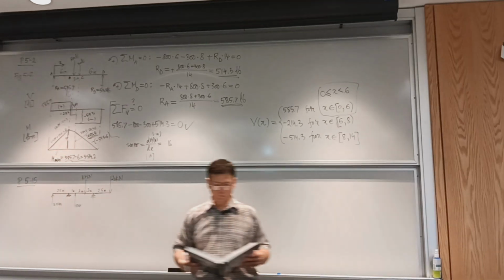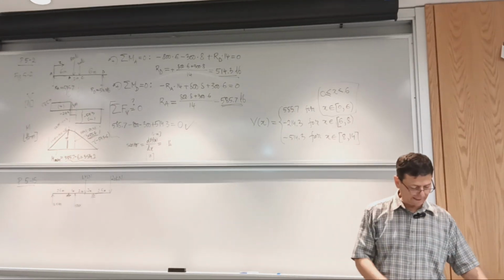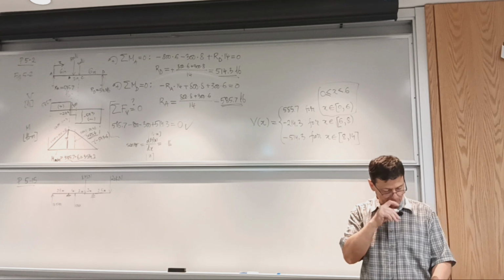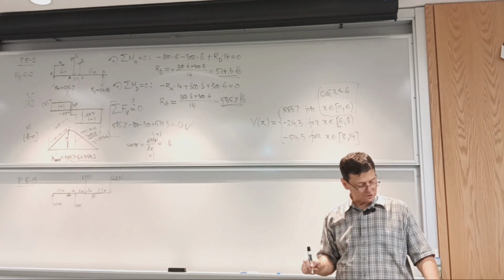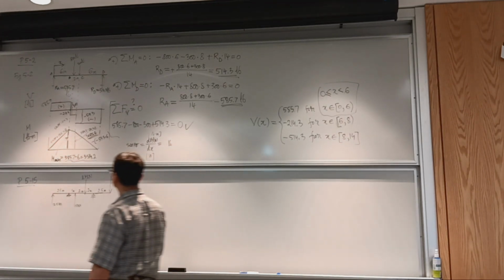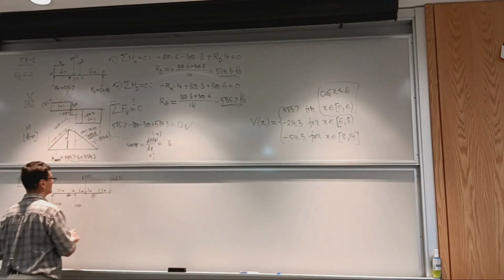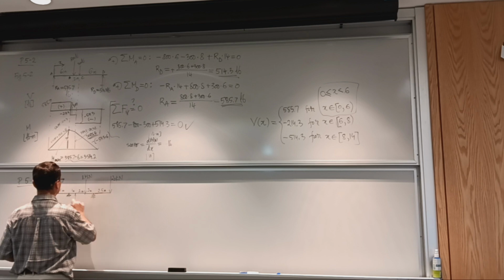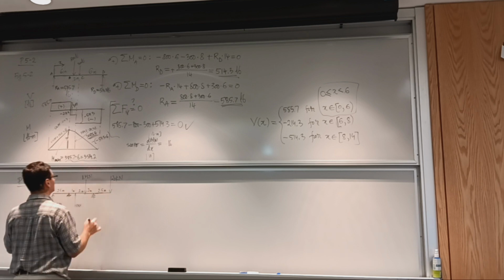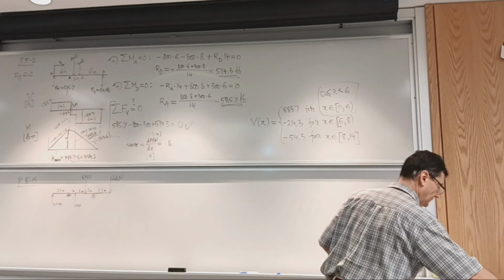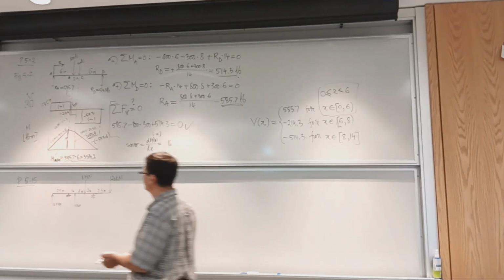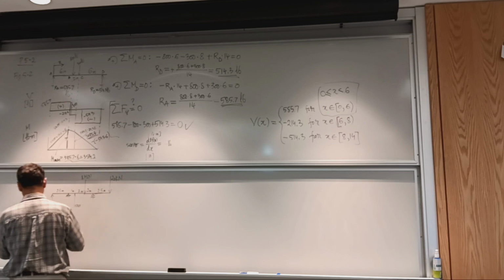Okay. The book orients the reaction but does not show the magnitudes for us to solve. The first one to the left, it shows us goes down. We don't know from the beginning, so we can assume a positive, and if the sign ends up being negative, we need to flip the force. Does it make sense what I'm saying? Let me label points.